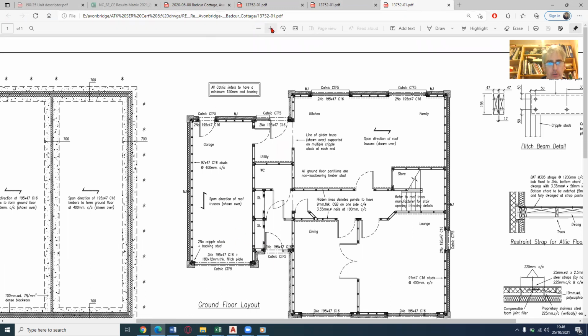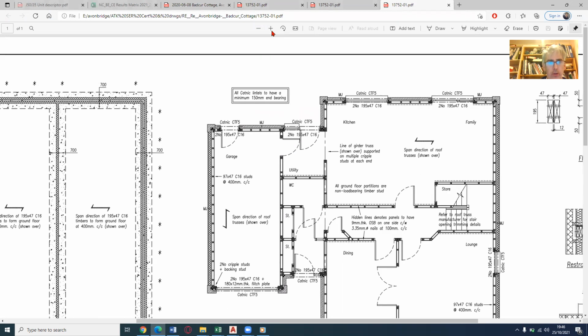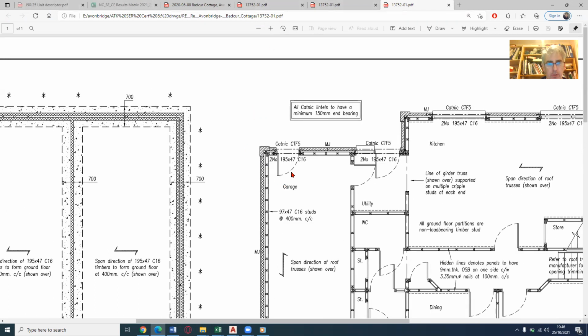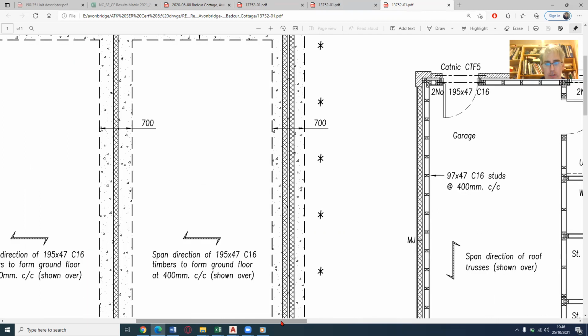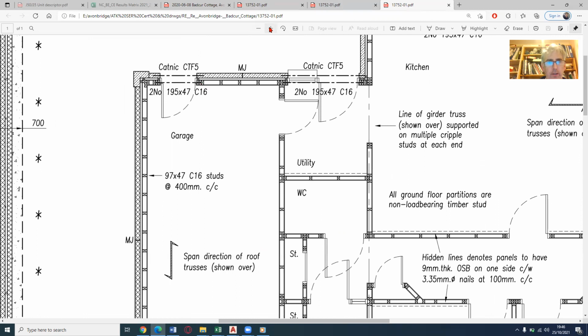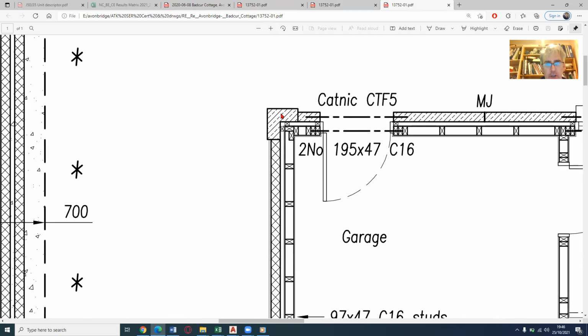So the external part of this house is reconstituted stone. Okay, so reconstituted stone, it's kind of got a crisscross shape. Mind you, that could also be blockwork. This is probably more accurate when you see the hatching here, where you've got a solid line and then a dashed line and then a solid line and then a dashed line. That indicates stonework. And then this here is going to be blockwork.